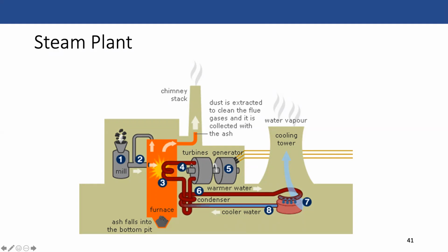Okay, so you get this hot steam passing through the turbine, which spins the turbine, right? And again, keyword is spinning here, which allows you to take advantage of a generator. And so that generator takes that spinning and turns it into electricity. Okay, great. And so then you've got some water that's condensed out of the turbine. So all of that steam passes through, gets cooled down, and then passed back into the furnace.